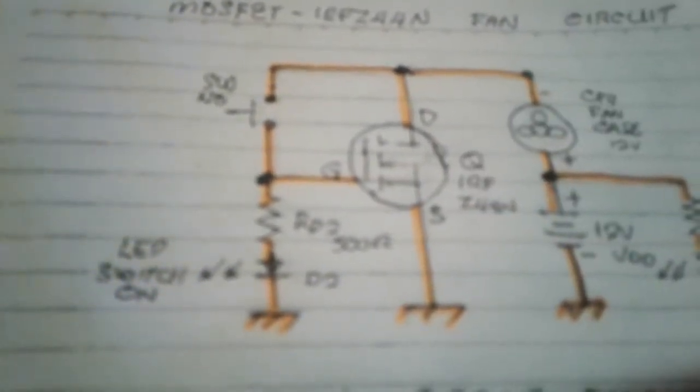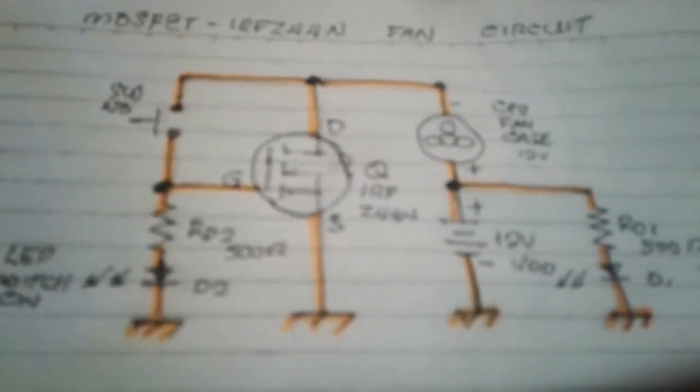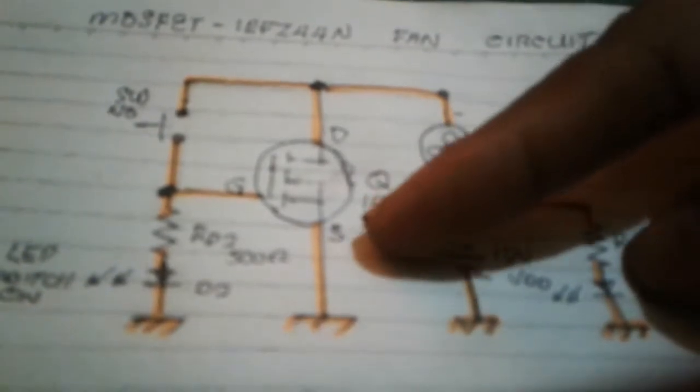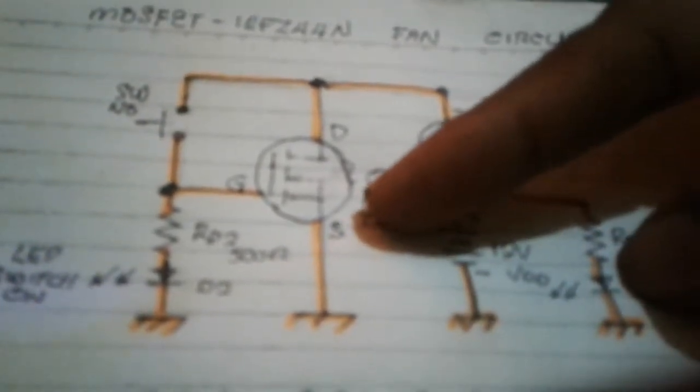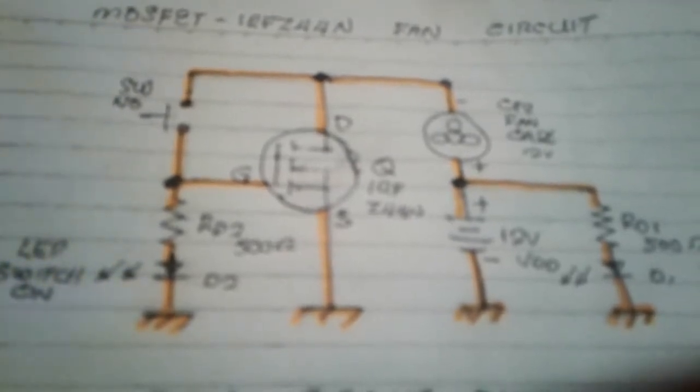The minimum voltage requirement for this Mosfet is around 4 volts to turn on this component. And we use this Mosfet as a switch, making this Mosfet to operate in ohmic region or in linear mode. Just like in BJT transistor saturation mode.